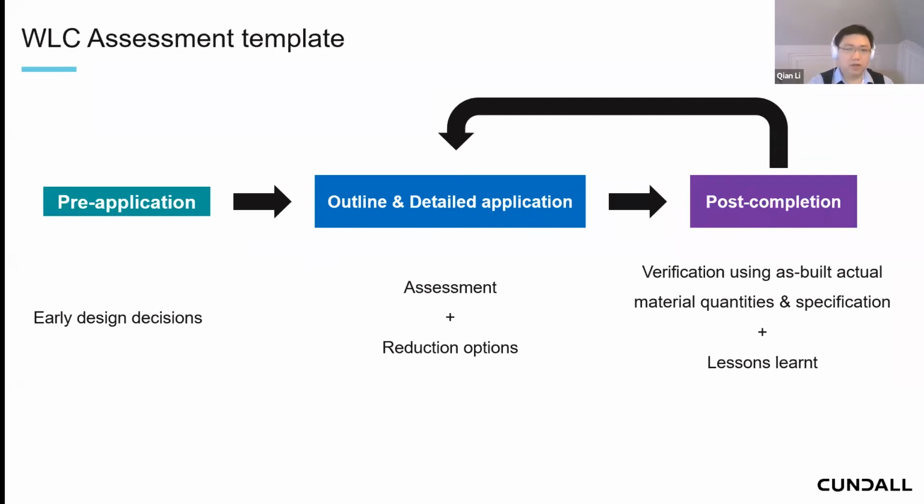So if there are any structures on site you could retain, or anything you can utilize and reuse on site, those early stage decisions will have a much greater impact if they can be considered from day one, or when setting out the brief. And when you have more information, you are ready to apply for outline or detailed planning application.